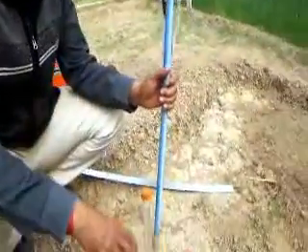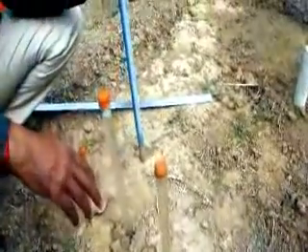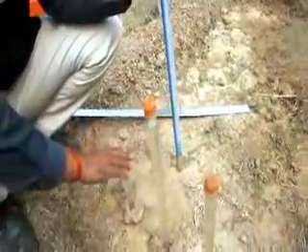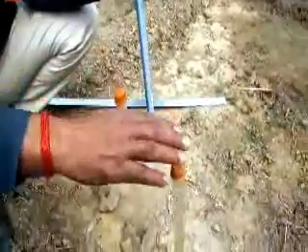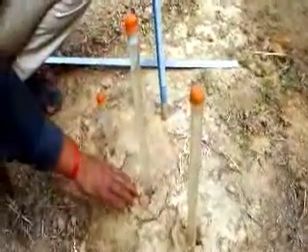Let me show you the other two methods: one is the tensiometer and another is the FDR method. We are using them in our farm to find out the soil moisture at the current condition. These two methods we will calibrate, or compare, using the gravimetric method. Now these are the tensiometers we have already fitted for our experiment at 30 centimeter depth, 45 centimeter depth and 60 centimeter depth from the top surface.